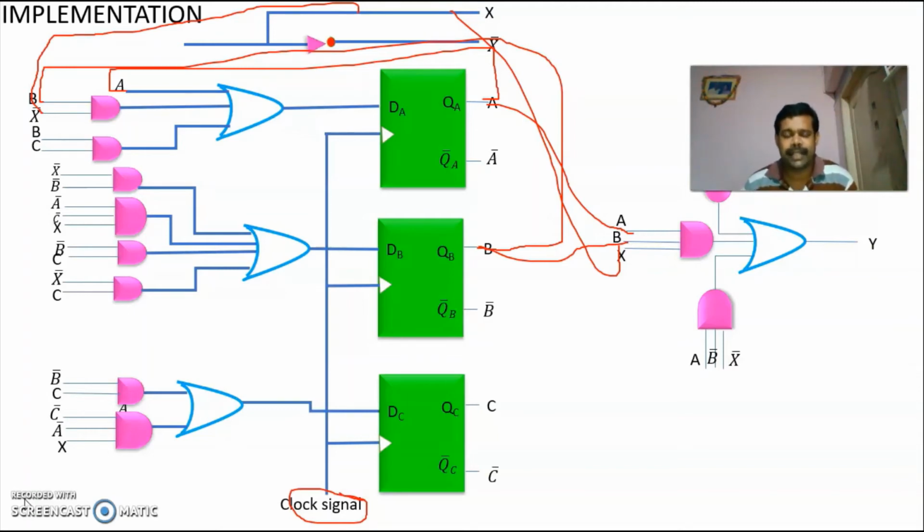After reducing the state table, you have to go for state assignment. The number of bits depends upon how many states you have. So in this problem, you have 5 states. The minimum bits required to represent 5 is 3, so use the 3 variables A, B, and C.